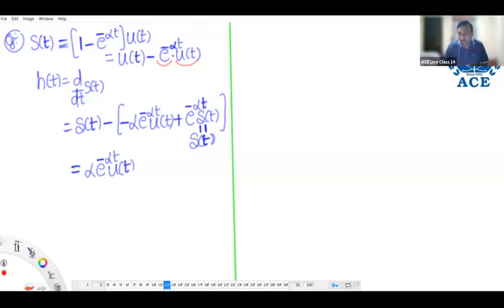Simply, differentiation of the step response is the impulse response. But practically this approach is never followed, sir. Because from the step response, if you want to get the impulse response, what is the system to be designed? A differentiator. Probably you are aware, differentiation in time amplifies the high frequency components of the signal. Generally we learn that a differentiator acts like a high pass filter and an integrator acts like a low pass filter.